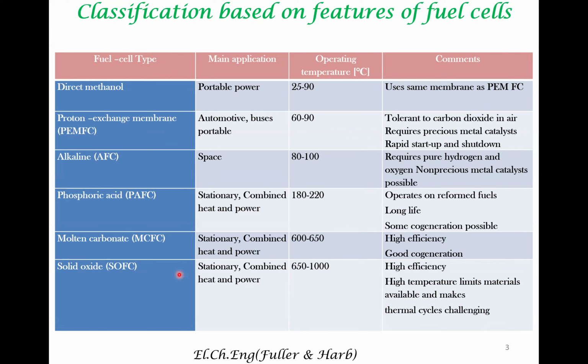There are many companies that have been attempting this, and there are some other companies that have been attempting SOFC. So, especially for transportation systems, PEMFC looks like a good option. In terms of stationary power generation using fuel cell, SOFC looks like a good option.